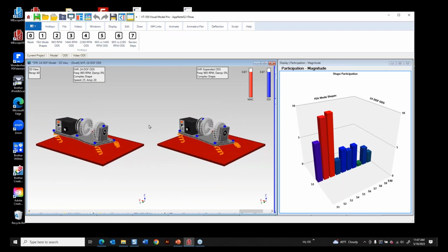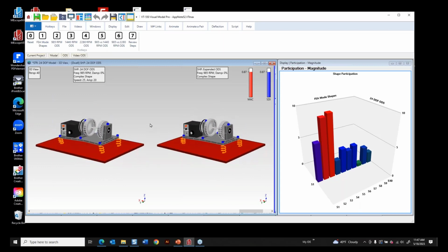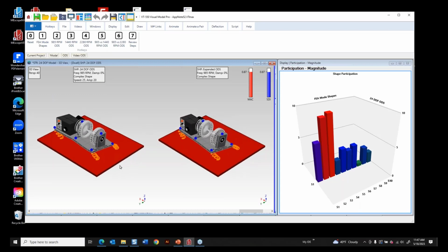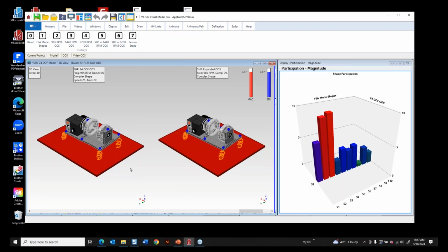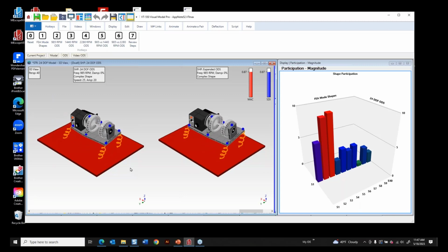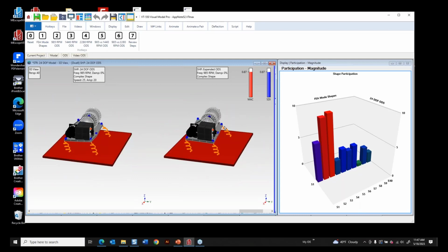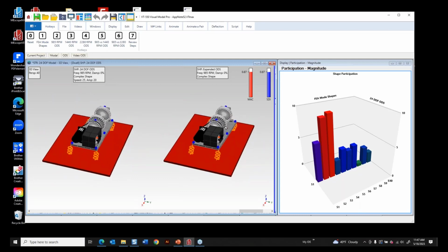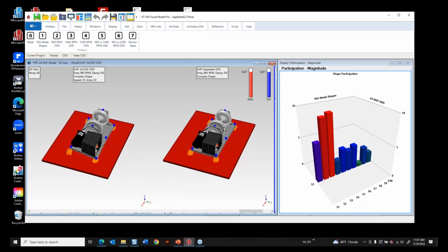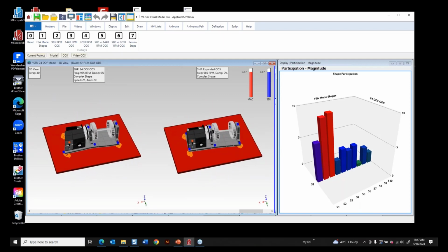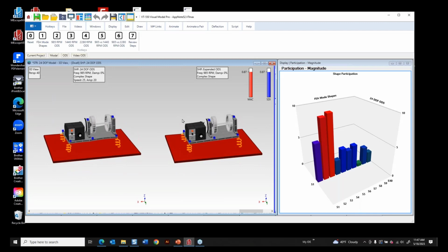Those weren't modeled in the FEA. We just had the free mode shapes. And then the rest of the animation here is what we call geometric interpolation. That's another feature in MEscope, where I've only got 8 measurement points and 3D motion at each of those points, but I've got a lot more points in this model. So they're all being animated with interpolation.